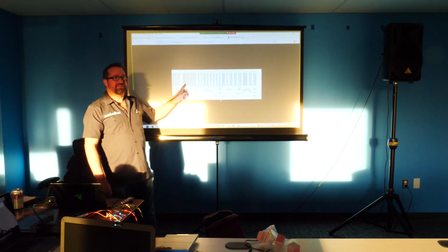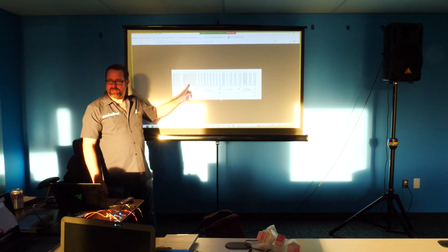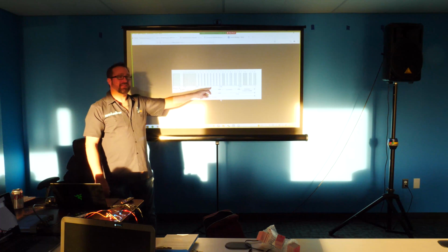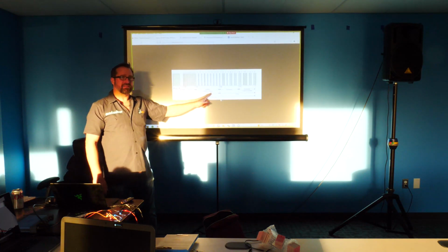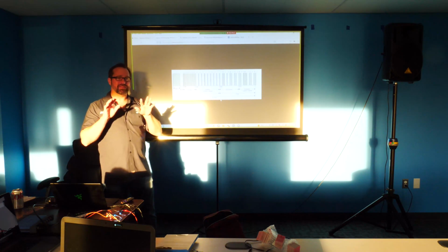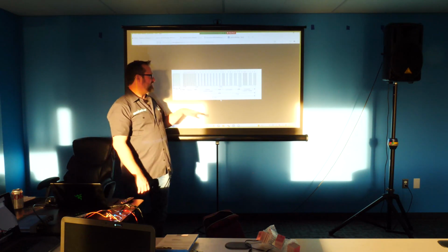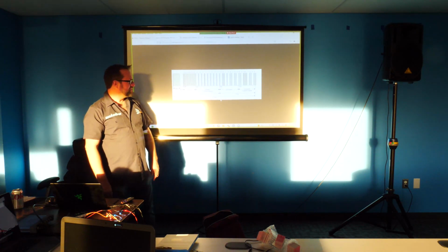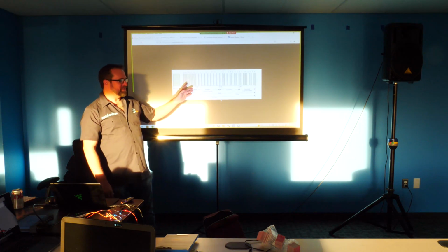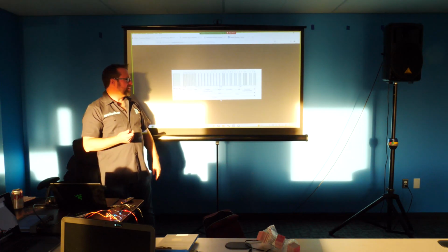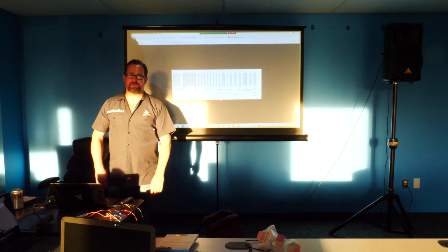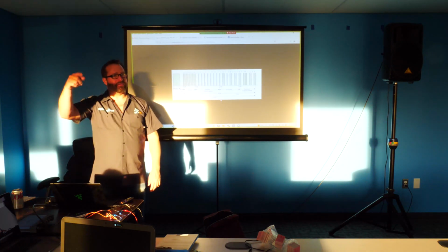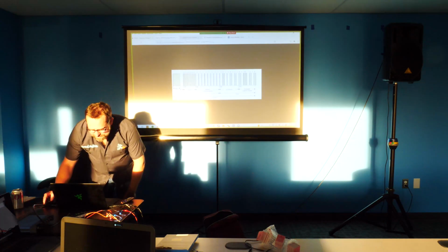But you'll see that this whole code is a fixed length in time. Even though the bits vary in length, so zeros are shorter than ones, the fact that you did the logical inverse means that 2 bytes that are inverse to each other take the same amount of time. It's kind of interesting. When you look at it on the scope, if you hold the button down, this actually will repeat multiple times. So if you're hitting the volume, it's going to keep going up. Now let's look at the code.